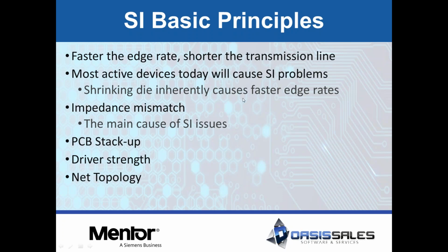Yes, you're right. That's probably one of the big questions. Well, the IC manufacturer can control slew rate and slow down the edge rates, and they do to some respects. In fact, the part I'm going to play with actually gives you an option. It's a little microprocessor that many of you may be using today that has different output currents that you can choose from, which is a big part of how signal integrity can be controlled, is how hard you're driving that signal down the line. 2 milliamp, 4, 8, 12, 24 milliamp drivers can all make a difference in signal integrity as well. And you can play with some of that on these devices, but some you can't.